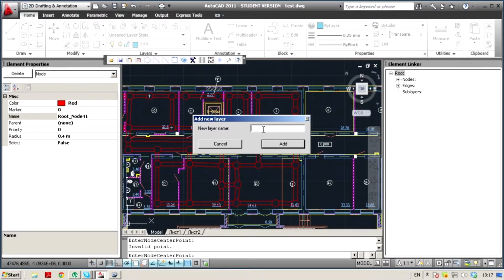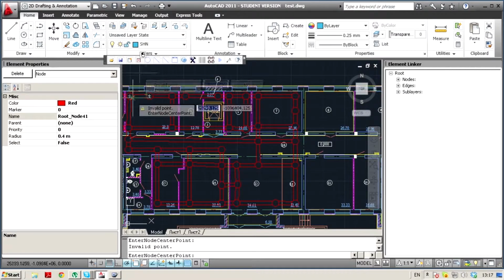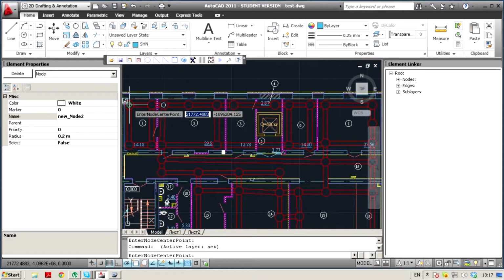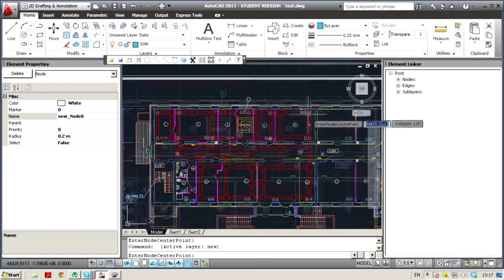As soon as you have created the layer, you can locate outlets in the already set nodes of the primary network. Each outlet has its corresponding properties. For example, you can set the size, weight, and color. Then you choose a specific outlet and define it to be the router switch.